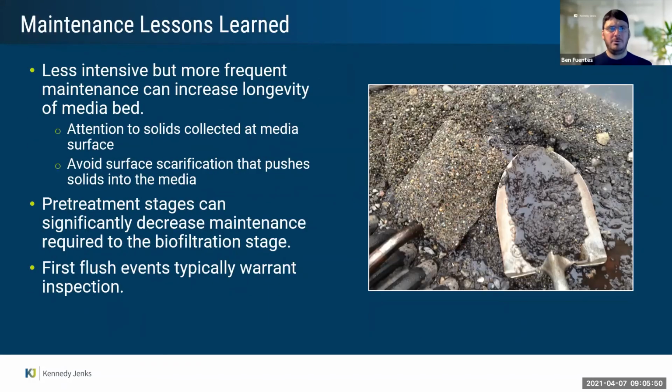So yeah, a couple lessons learned. The most obvious, less intensive but more frequent maintenance will significantly increase the longevity of your media bed. Pre-treatment stages can be a big benefit to increasing the longevity of your more expensive media downstream if it's biofiltration or polishing media. And that, after a first flush event, you're likely going to want to get out there, get eyes on it, and probably do some solids removal.